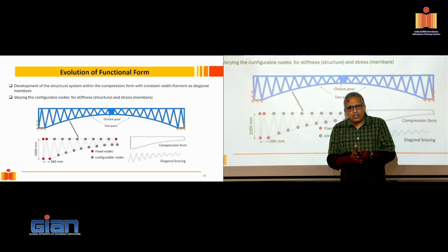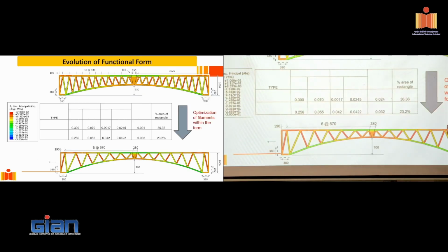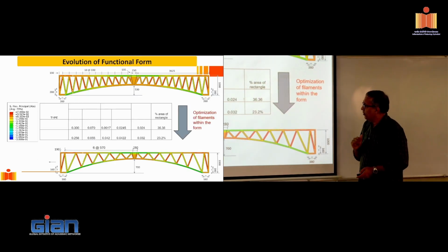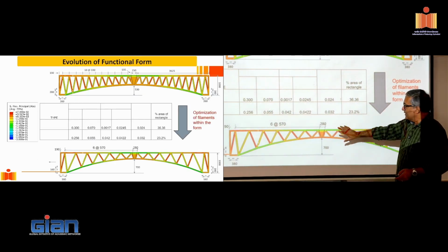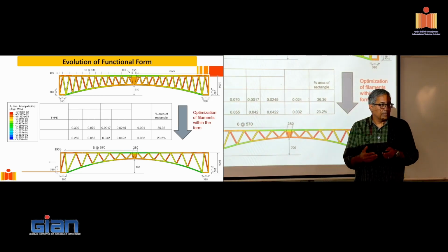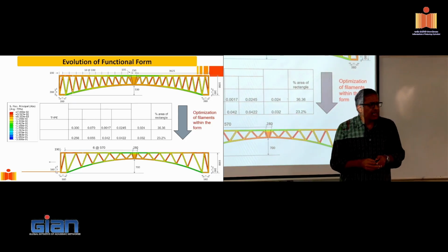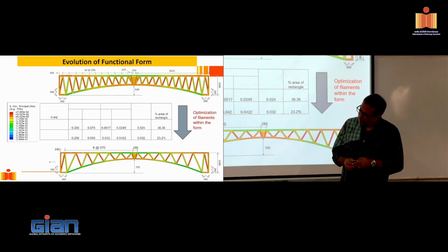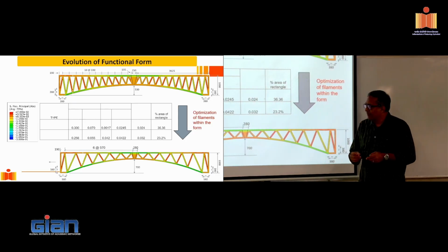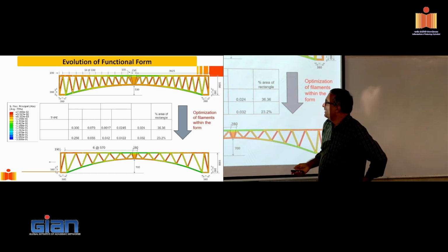Right? So we did a lot of iterations with the lattice structure, and the objective was not to compromise on performance. What performance are we looking at? We're looking at the stiffness of the bridge and the load carrying capacity. What is the maximum load that it can carry? Some of the diagonal elements have to be in tension, right? They are in tension, a small amount of tension. And for that we did introduce a little bit of reinforcement. I'll just show you what happens there.